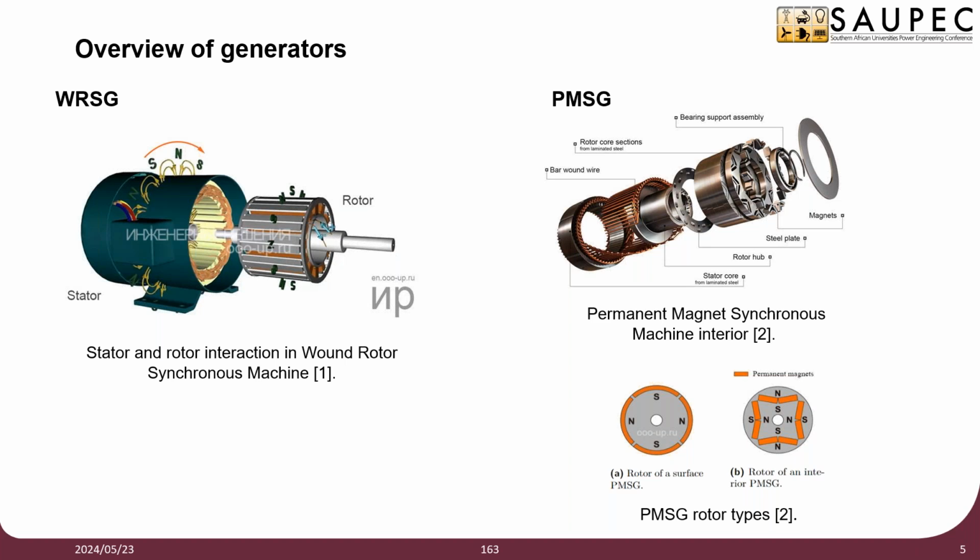This study made use of rectangular open slots for ease of design and potential manufacturing, as the coils are preformed and then slotted in. The PMSG is a brushless design using permanent magnets for superior power to volume and torque to inertia ratios compared to other electrical machines.